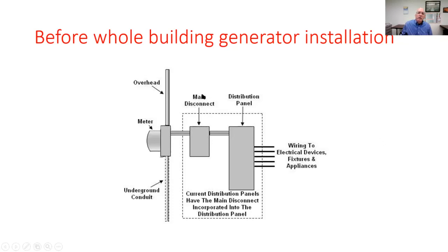And you'll see that whether it's a main disconnect or the whole house transfer switch, this is where your grounding and bonding originates. You have to come out of this main disconnect or whole house transfer switch and go to your ground rod. Or if you had building steel in some type of dwelling unit, that would serve as the grounding electrode also.